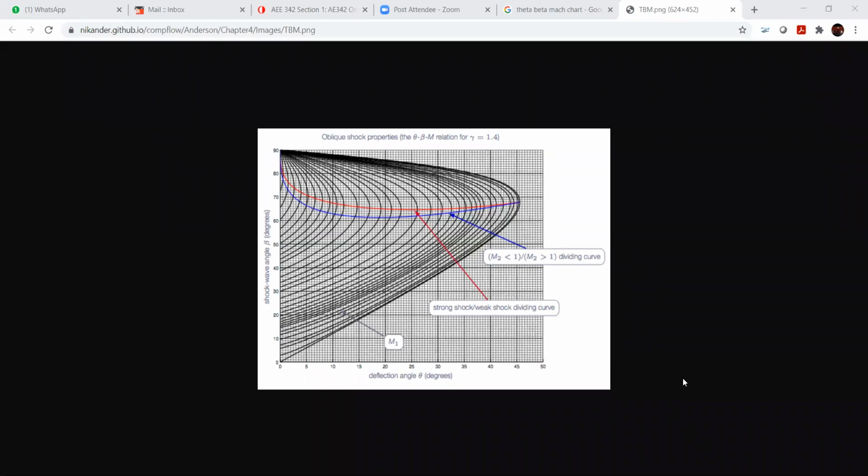Any other questions? Yes. Can we say that an accelerating supersonic aircraft would be exposed to a detached shock wave somewhere during acceleration? Yes, you can say that. It could be, unless it has a variable geometry. Generally, the nose will not be variable, but as I showed you in the very beginning of this class, some aircraft have variable geometry intakes, depending on the aircraft design.